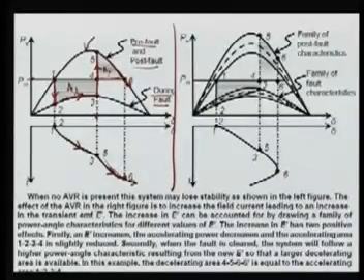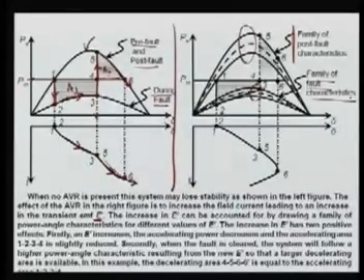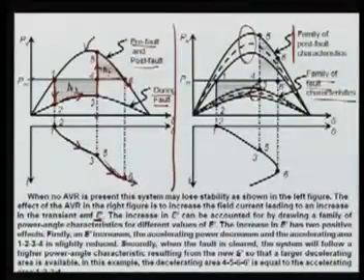The effect of AVR in the right figure is to increase the field current, leading to an increase in internal EMF, that is E prime or EF we are trying to increase. Now you can see a different family of curves. These three curves are the family of post-fault characteristics, and these three are the family of faulted characteristics, meaning during-fault curves. And again, if you keep on increasing EF, you will get different magnitude and different curve shape.